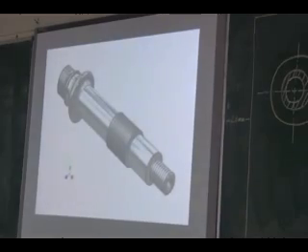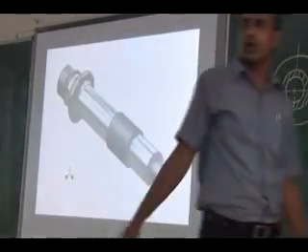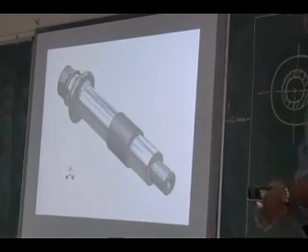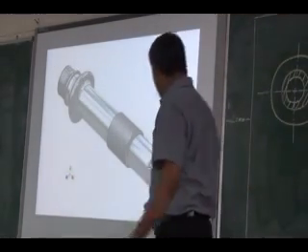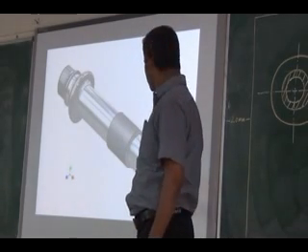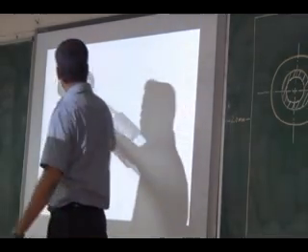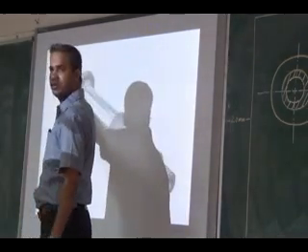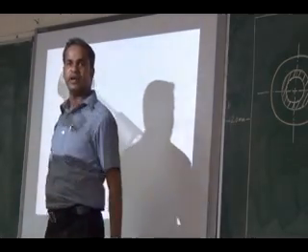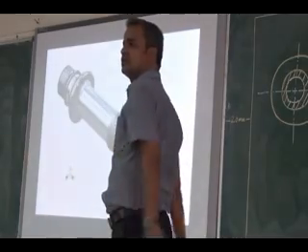You see the shaft drawing here. It is some shaft, and you have so many details in the shaft. See here, I have a thread at this end, a step here, another step portion here, so many grooves here, and then a thread there. This looks simple to produce.